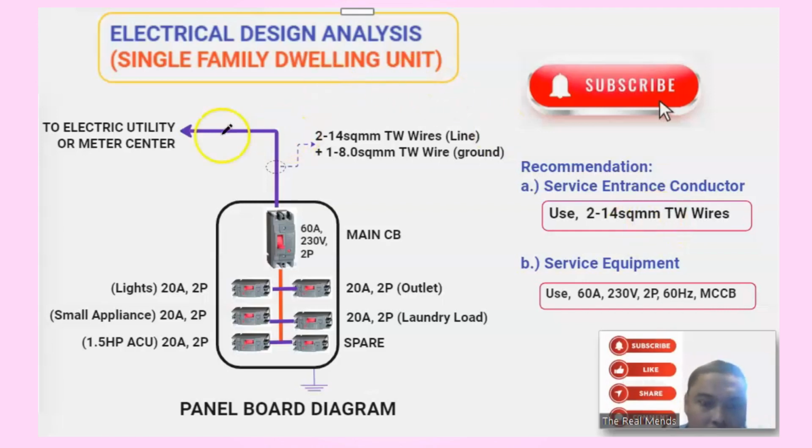Ito yon, is coming from electric utility or meter center. Okay, ito yung line. And then if we look on the PEC, that is 8.0 yung ground wire niya, TW din. Okay, so yung main is 60 ampere trip circuit breaker. Ito yun.